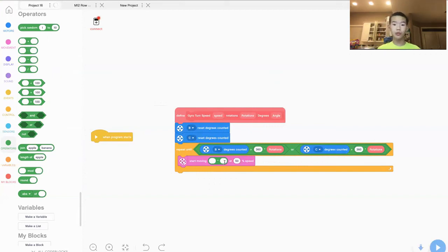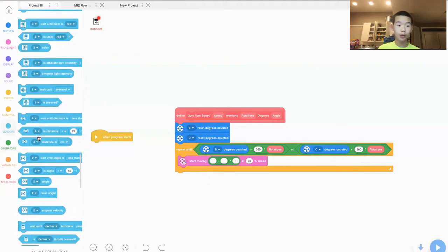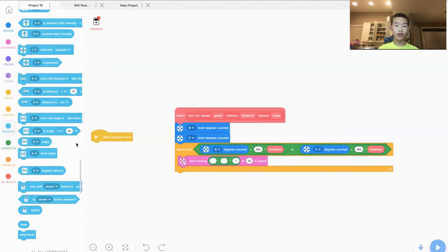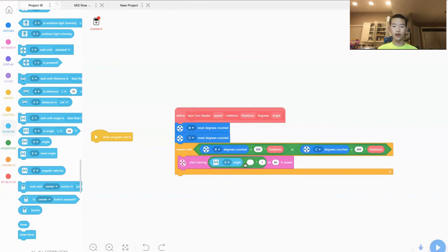button, and you want to input 1 on the right, and add a subtraction operation on the left. Then go to sensors, click on the gyro, go to the gyro section with the only oval shaped block for the gyro, and plug it into the first slot of the subtraction operation. Change it to 1, because that is the port for our gyro sensor. After you're done with that, you want to set the angle of it. And you are so close to being finished.